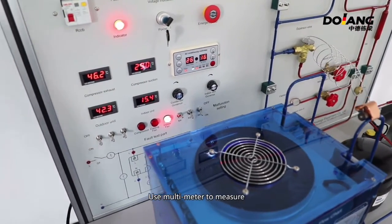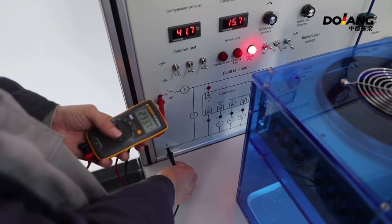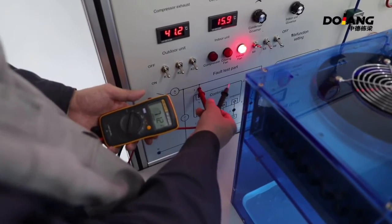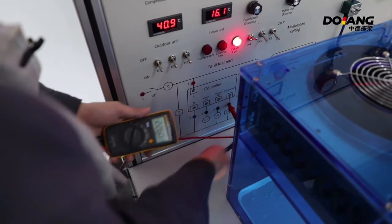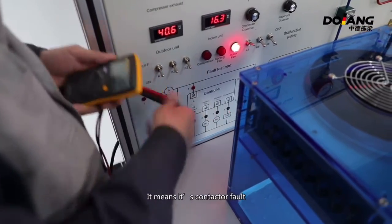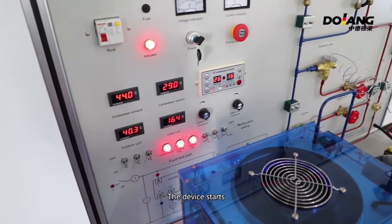Use a multimeter to measure. Found that there is no voltage at the contactor. It means it's a contactor fault. Turn K4 to on. The device starts.